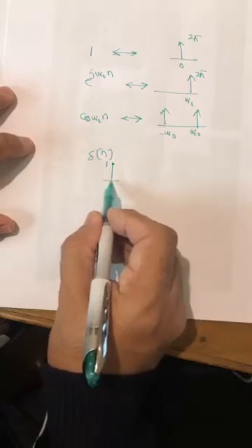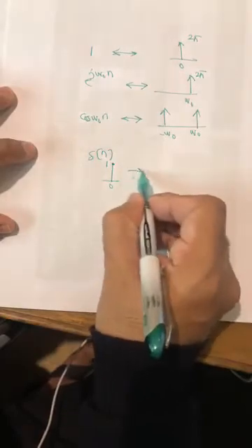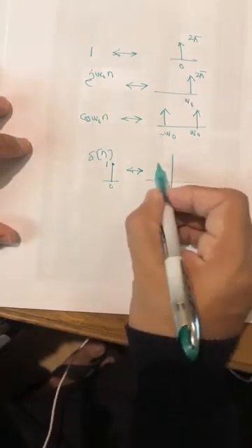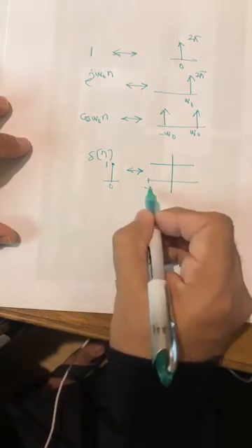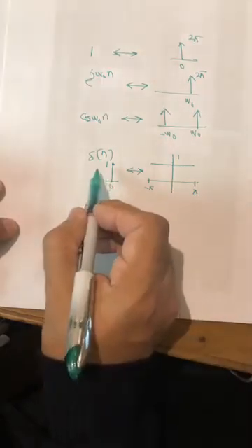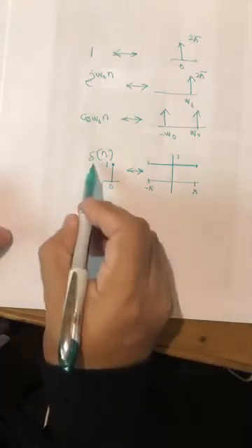generating an impulse, which is a signal, and then it goes back, you find out that there are not one, there are all exponentials, all possible perceivable exponentials with the same magnitude. So an impulse has all the frequencies in it. Okay, so delta of n has all the exponentials in the entire spectrum of the same magnitude. So delta of n has all exponentials.